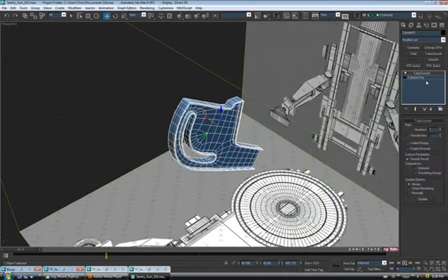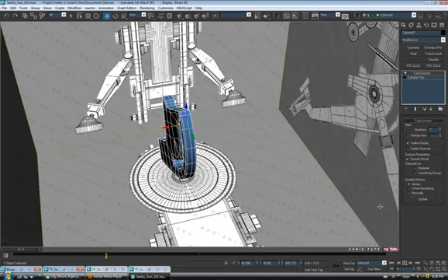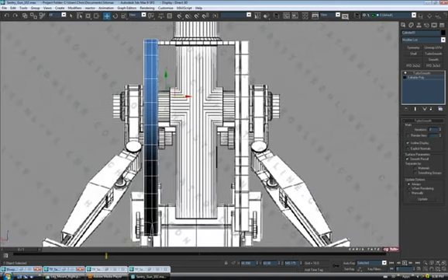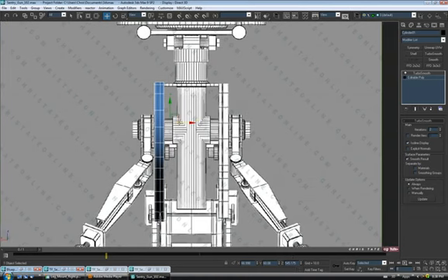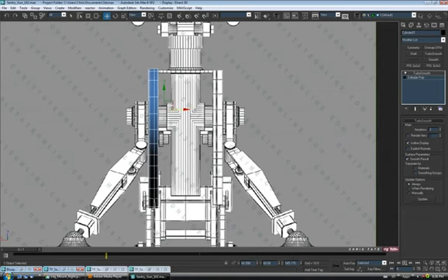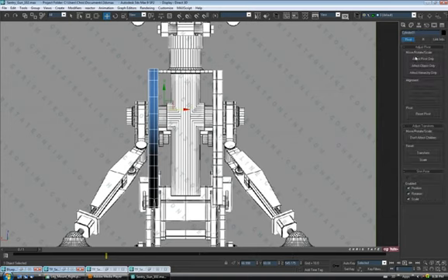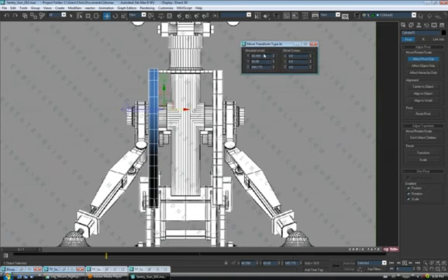All right, so let's just put our turbo smooth back on. We'll do our 2 iterations in isoline, and we'll just copy it over to the other side in the back view here. All right, so you can use symmetry if you want to mirror it over. I think I might just use mirror. Let's just move our pivot point over to the center here. So we'll go into the hierarchy tab, turn on effect pivot only, and I'm just gonna right click the move tool to bring up the move transform type-in, and we'll just zero out the X spinner. Okay, it's going to snap the pivot point to the origin.